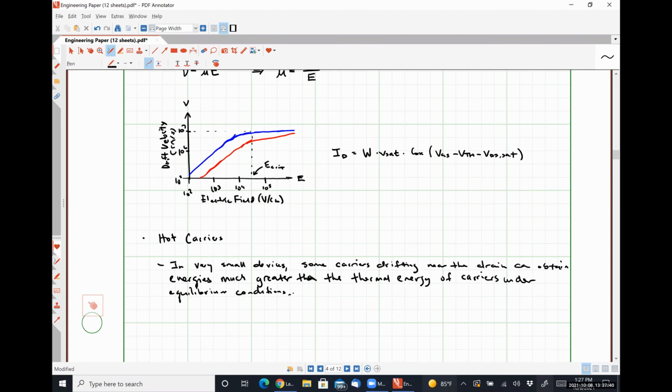We have a similar kind of situation here as to what we just talked about with velocity saturation, except that the problem with these hot carriers, so we were imparting a lot of energy into these electrons as they're trying to go from the source into the drain, right? The ones that make it all the way across hit those lattice vibrations and wind up slowing down.